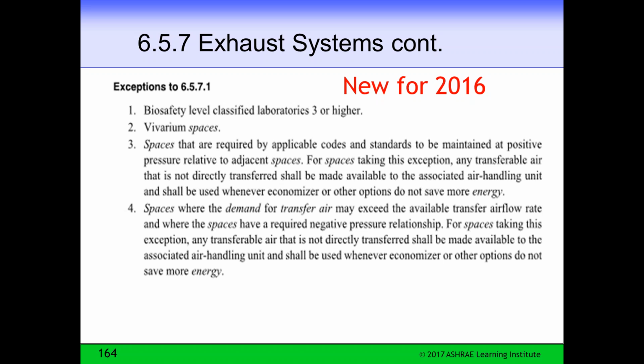Spaces where the demand for transfer air may exceed the available transfer flow rate and where the spaces have required negative pressure relationships. For spaces taking this exception, any transfer air not directly transferred shall be made available to the associated air handler and shall not be used whenever economizer or other options do not save more energy.